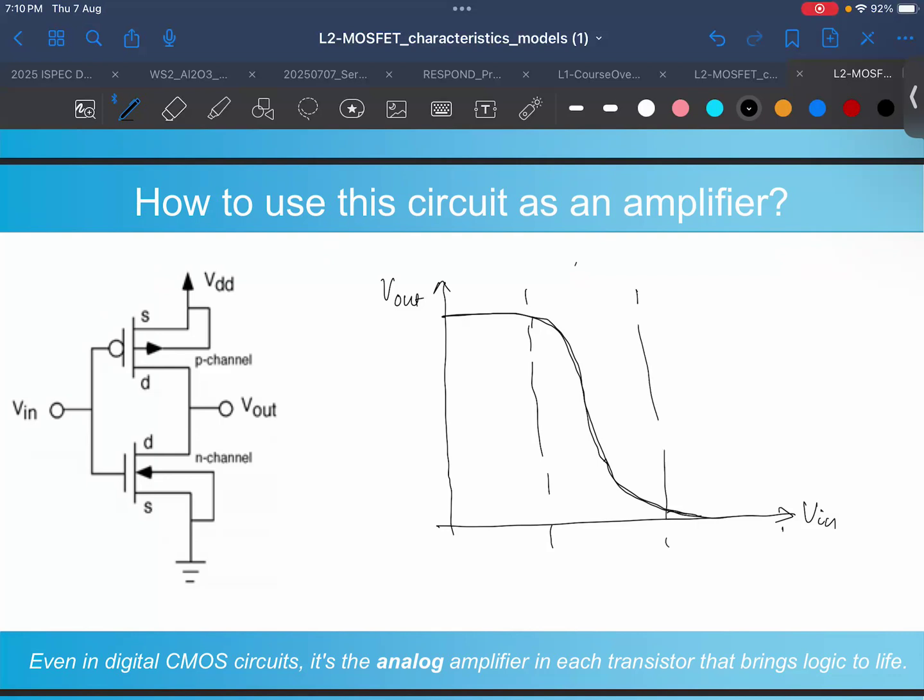This is your region 2 which we said. And where would you put this signal? This is obviously 0 to VDD, with VDD being 1.8 volt. And we have a signal coming from a microphone, let's say, as we talked about. This is a few millivolts, or let's say 100 microvolt. That is the V versus T we are talking about.